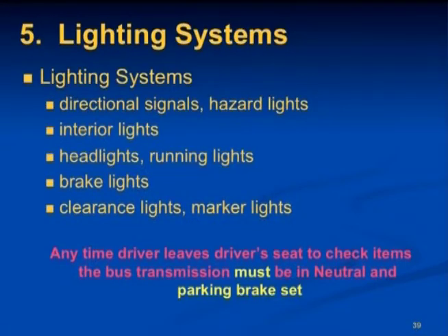All right, continuing with our pre-trip, after you've started the bus, now we're going to check the lighting systems. All lights and lighting indicators should be checked for proper operation, adjustment, and color on the front, rear, and sides of the bus. They can be wiped clean during your walk-around. They should turn on when the appropriate control is turned on.